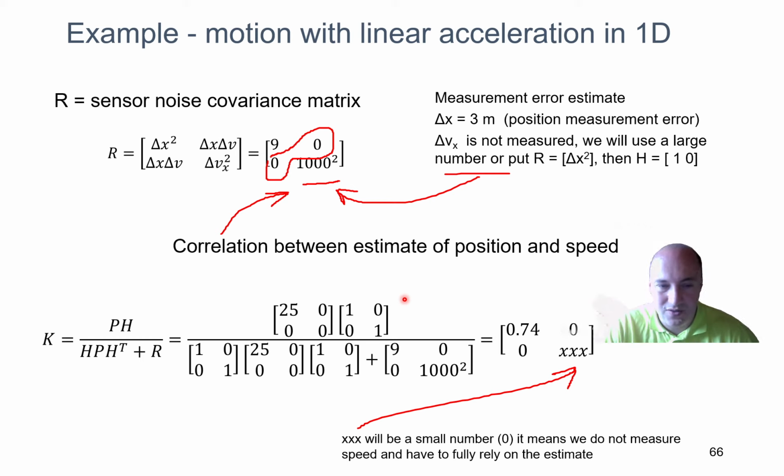In my opinion, it's easier to understand if you choose the format of your matrix in the same way as you have all the other matrices, and you put here just a large number that says that you do not measure that. I think it's easier for more variables, because you just put a large number and the matrix H is still the same matrix, so you just generate the matrix, even for more variables, which has ones on the diagonal, and that's super simple.